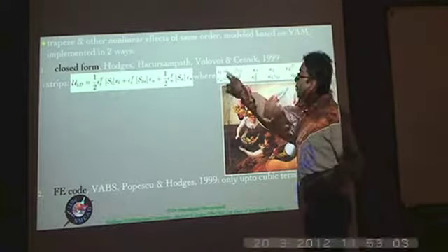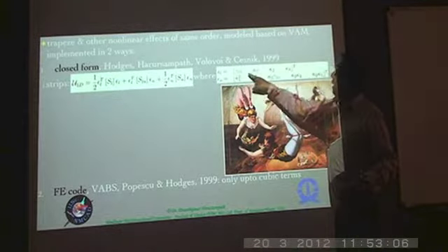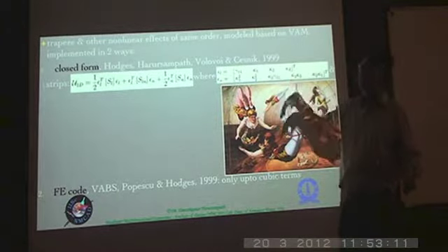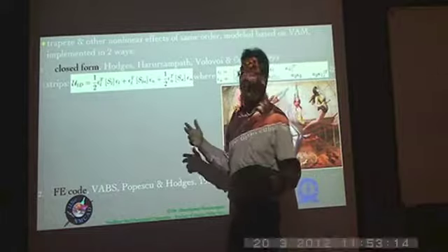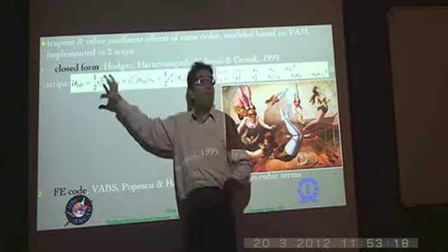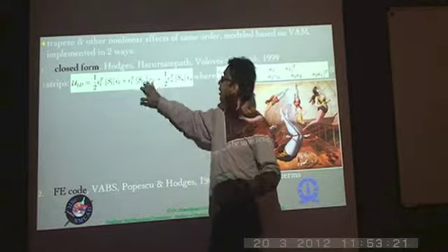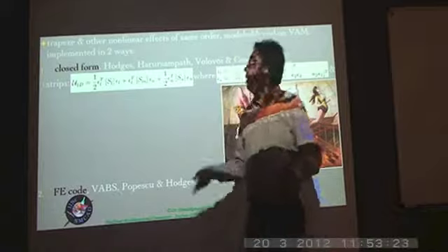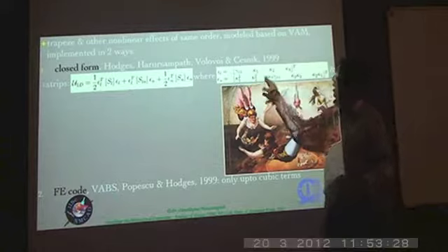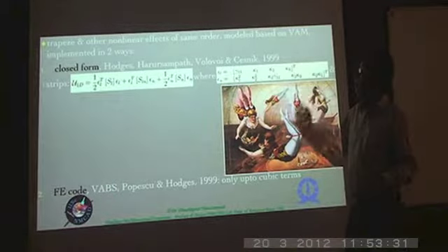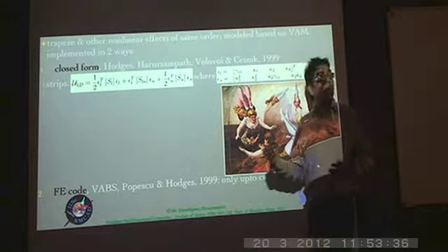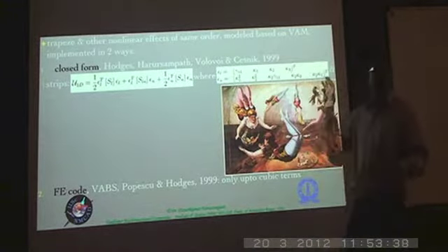So here the first term involves the extensional strain, the twist per unit length, and the two bending curvatures, and basically the cross couplings between them. But because SL is a matrix of constants, it's only the linear effects which are present here. But these two additional terms couple that epsilon L with an epsilon N, which consists of quadratic terms. But note that not all quadratic combinations are present. Only those which are asymptotically relevant at that first order are included over here.